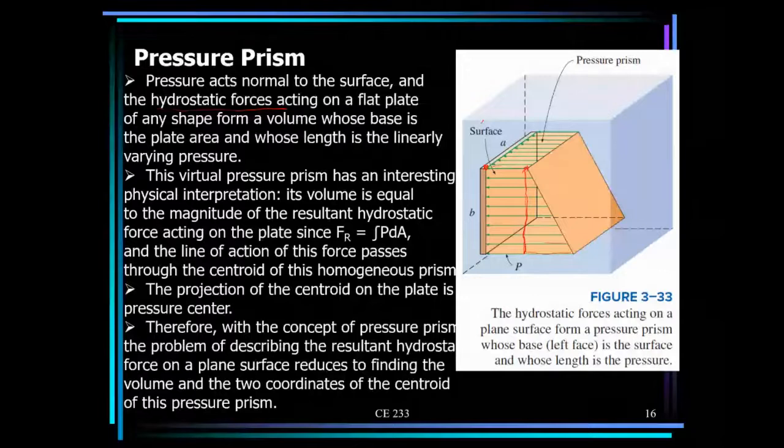And how do we find the volume? In this case, it is going to be the integral of PdA. If we find the area of this trapezium here and multiply by the breadth B, that will give us the volume, and that will give us the resultant pressure force.